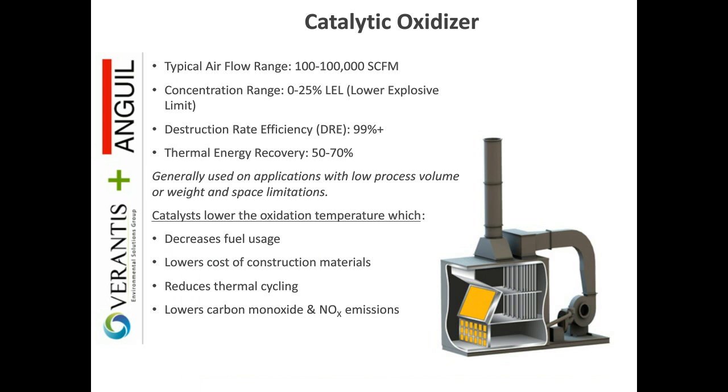The next technology, catalytic oxidizers. I just have one slide on each of these next few technologies. We say here typical ranges are in the 100 to 100,000 CFM range. In reality, they tend to be more applicable to the smaller ranges. I would say the vast majority of catalytic oxidizers are applied in the 100 to probably 5,000 CFM range. The reason is that 5,000 CFM is right around the size where the RTO is actually cheaper in terms of capital cost and operating cost. So we see very few catalytic units sold bigger than that.